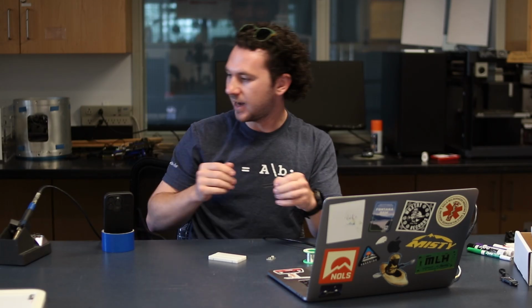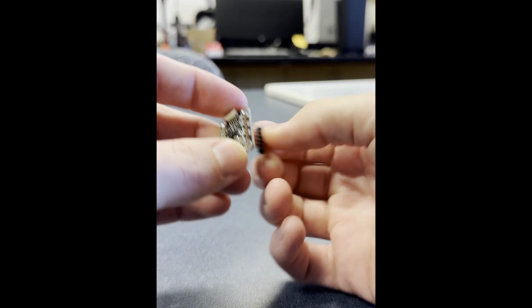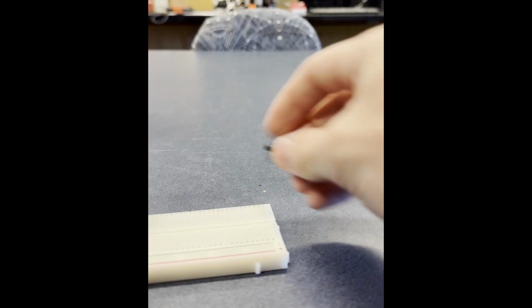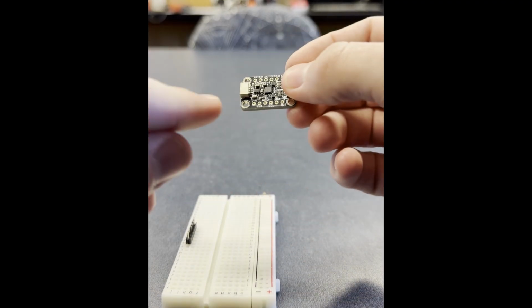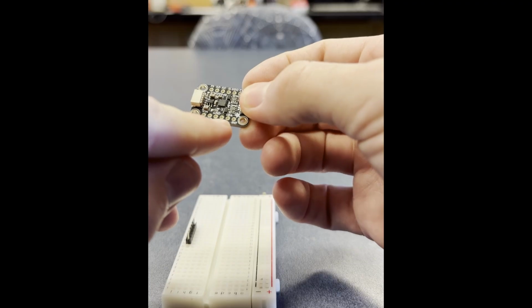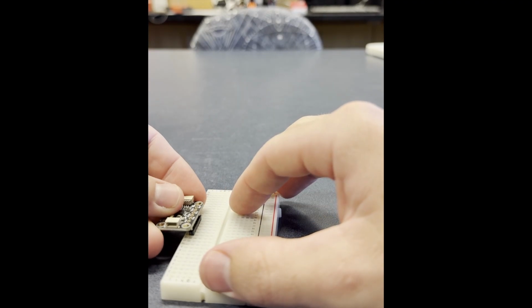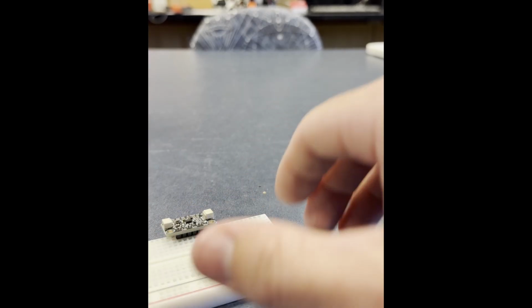What we're going to do is snap off 6 header pins. Come down here, make sure I grab 6. 1, 2, 3, 1, 2, 3. There we go. That should be 6. So let's test it. Lovely. That fits. All right, so I'm going to take my header pins and press them into a breadboard like we did before. I'm going to make sure I get the side with V in, ground, SCL, and SDA, because SCL and SDA are the pins we want to connect for that I2C protocol.